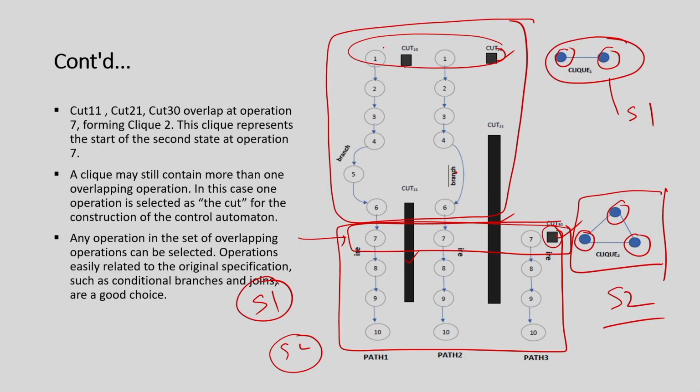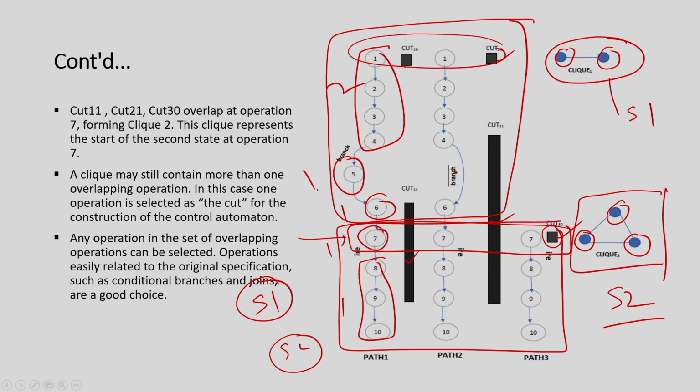Earlier, if you just think about this same program, this part probably needs 2 states, this needs 1 state, this needs 1 state, this needs 1 state, this needs 1 state, right, because these are all loops. So, 2 plus 1 plus 3, 4, 5. You need at least 5 states to get the complete schedule if I go by basic block based scheduling, but here I can understand that everything can be done in 2 states. So, the number of control states obtained by this path based scheduling is minimal, right.